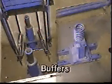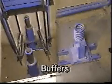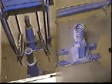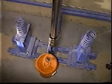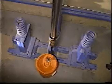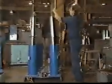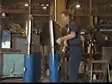Cushioning devices called buffers are located at the bottom of the hoistway in an area called the pit. Spring buffers are large coil springs, generally mounted on stands and used on low-speed elevators. The oil buffer uses a spring and reinforces it with an oil cushion, similar to a shock absorber on an automobile. This type of buffer is used on high-speed elevators.